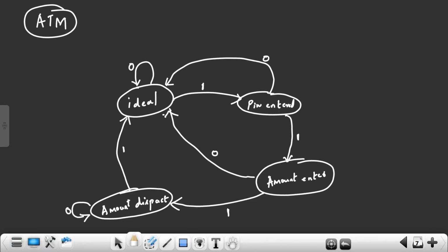So this is the behavior of your ATM machine. You convert it into an FSM. FSM means finite state machine. And for each state, you start writing the RTL code. So for this state, what is the input? I will take one variable for this input, card in. If card in is 0, you stay in the idle state. If card in is 1, go to the pin state.